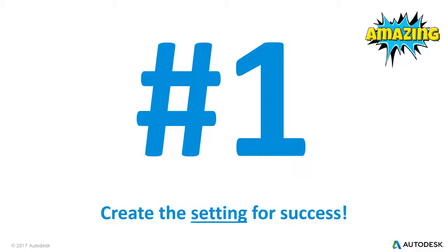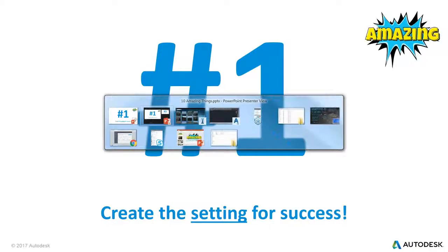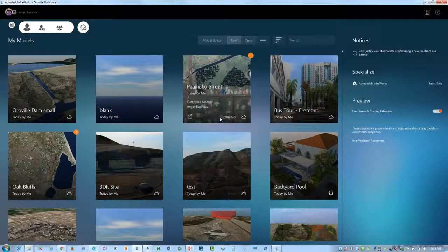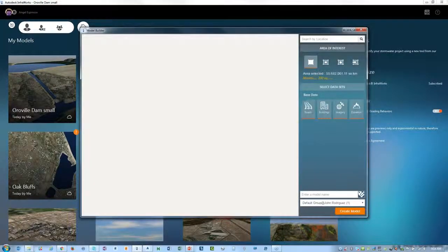Well, the first thing, creating the setting, probably one of the most important but fundamental things that InfraWorks is capable of doing, and I wanted to make it clear, this is part of InfraWorks and not part of InfraWorks LT, is the model builder. Now, to get to the model builder, if you're in the primary screen here, I'm going to hit the little plus icon, and that brings up the open and the new and the model builder. And I'm going to go ahead and initiate this.